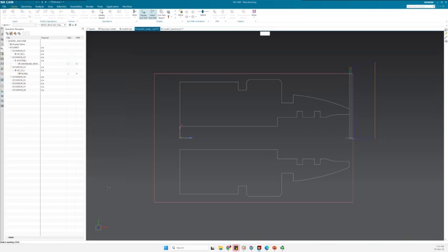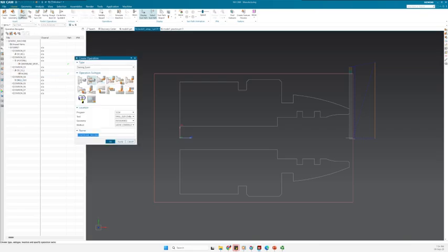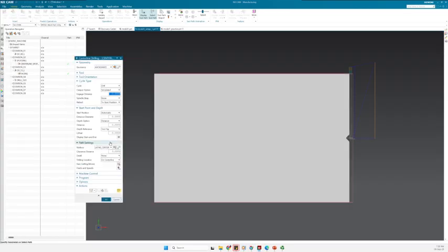All right. So I click this. Now I have my drill. Next, I will create a similar operation to the spot drill, but this time with the drilling one, same program. The drill is selected correctly. Again, the same vocabulary needs to be used here, avoidance, and same method of cutting. Center drilling, I have only one drill, so I don't need to rename this perhaps. So I can just leave it as it is.